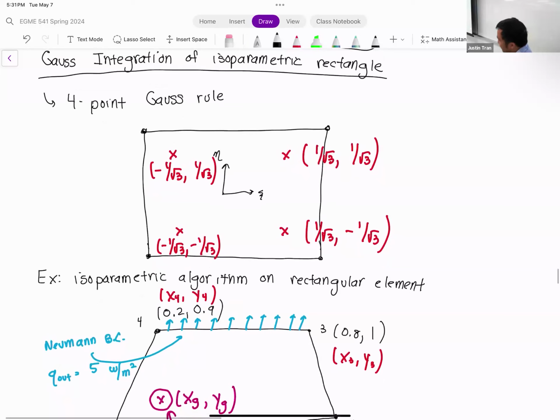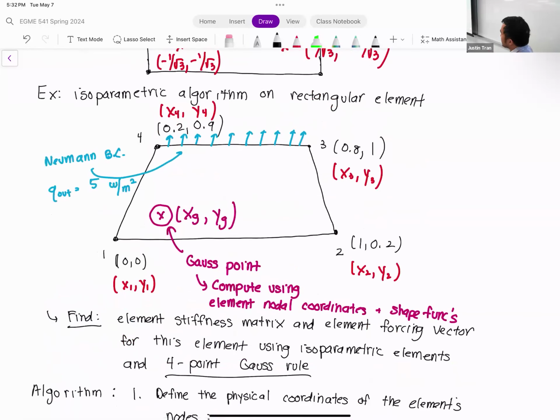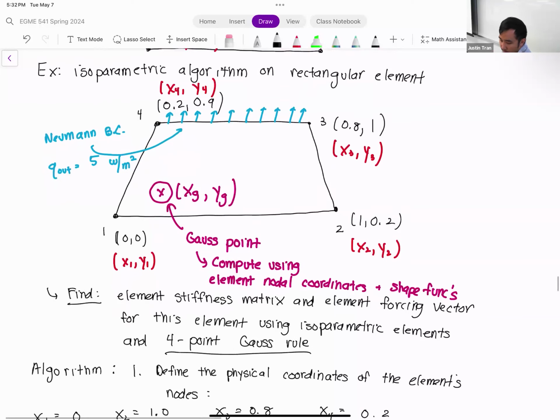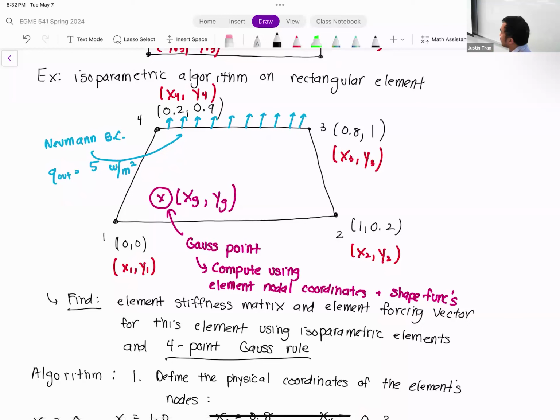Okay. Because what we discussed last week was that, for a general finite element mesh, your elements are going to be of arbitrary shape and arbitrary size. They're all going to have the same number of sides, the same number of nodes, but how they're oriented, their exact size, how they're distorted, that's all going to be different. If you think about your final project, you're working with a triangular mesh, all the triangles are different. They're slightly different sizes, located in different places. But we still have to generate an element stiffness matrix for each of those elements. And the way we do that is to use this technique called Gauss quadrature, which helps us evaluate the integrals in our expression.